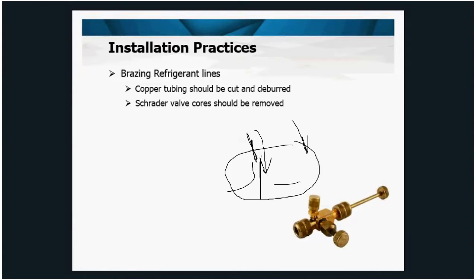This greatly reduces evacuation time. It's really hard to pull a lot of refrigerant around those cores, or a lot of either air or refrigerant, whatever you're trying to evacuate from the system, from around those cores. You take the core out, it goes much, much faster.